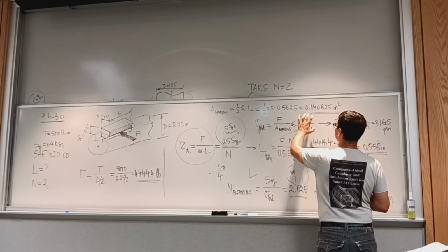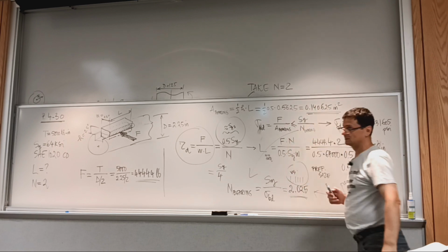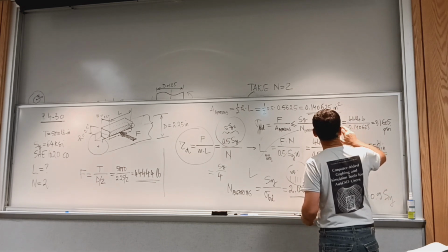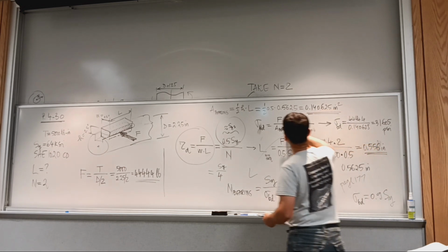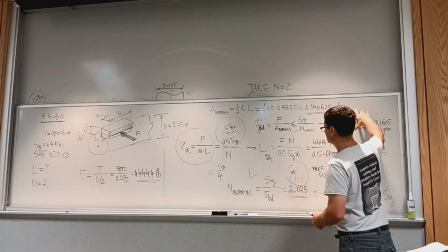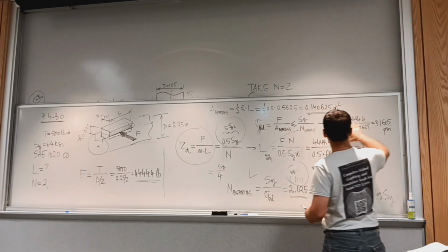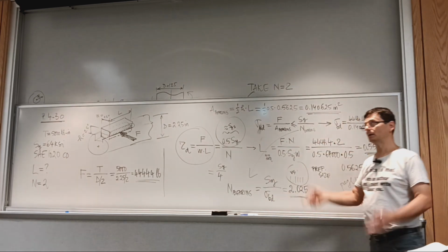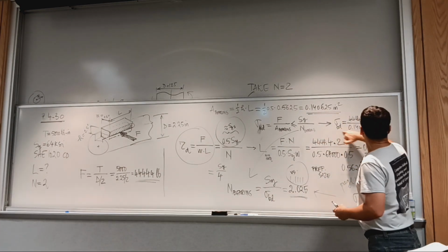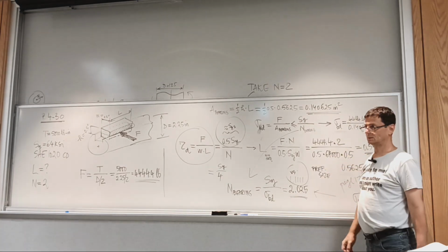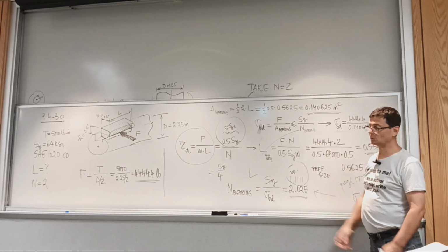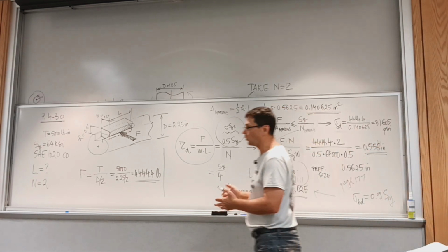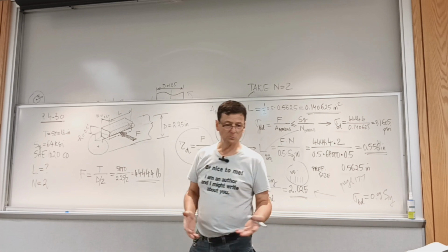You take the yield strength in tension and divide it by the design factor, which happens to be also 2 for machine design. And I calculate with this formula the bearing stress, and I calculate the design factor in bearing by taking the yield strength divided by the bearing stress, okay? So yeah, you may have to go back and read about bearing, but I hope the concept is clear. We did it in a hurry.